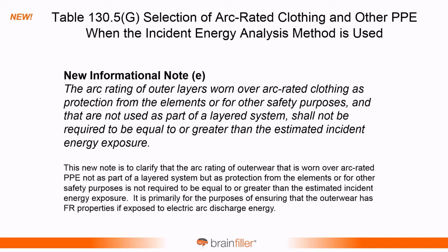So it actually specifically reads, the arc rating of outer layers worn over arc-rated clothing as protection from the elements or for other safety purposes, and that are not used as part of a layered system, shall not be required to be equal to or greater than the estimated incident energy exposure. So that's new. That's one of the additions.